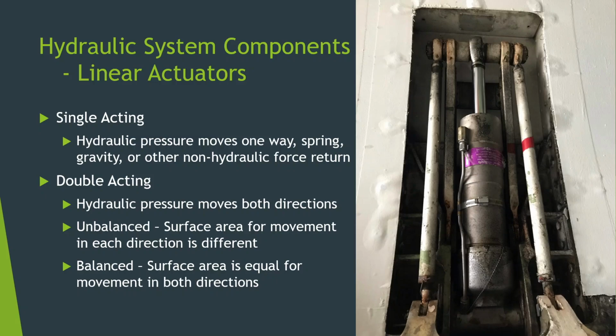In the case of a double-acting actuator, you have the ability to use hydraulic pressure to move both directions. And this actually is, even though it's a door actuator, a double-acting one. Like I said, it can be closed without hydraulics, but normal operation would be using hydraulics because that can be used to help force it shut to get it to lock. But in a double-acting actuator, we further break it down by whether an actuator is what's called balanced or unbalanced. And that refers to the amount of force that's available.